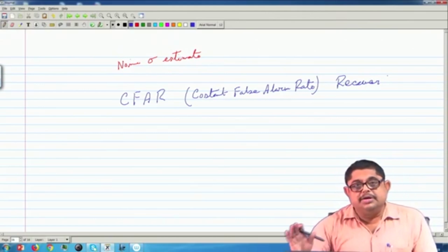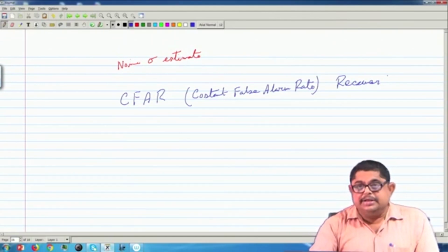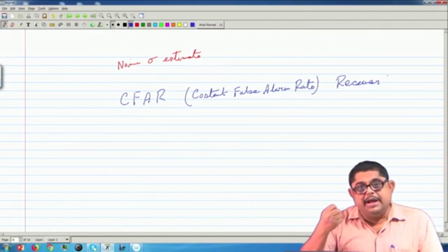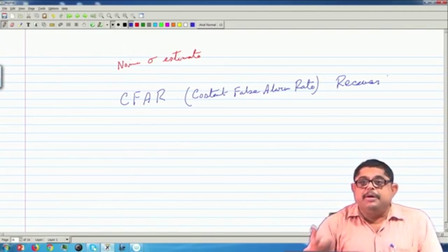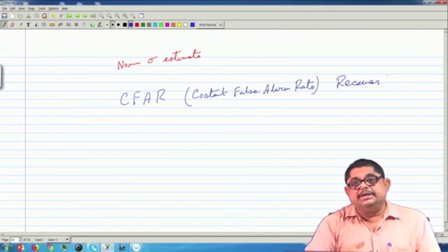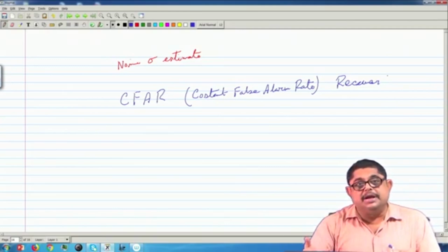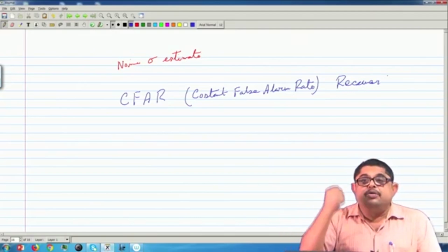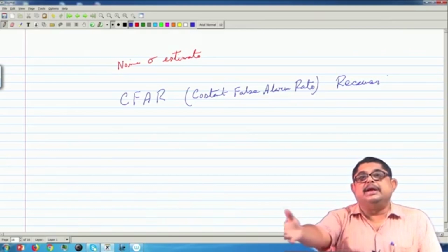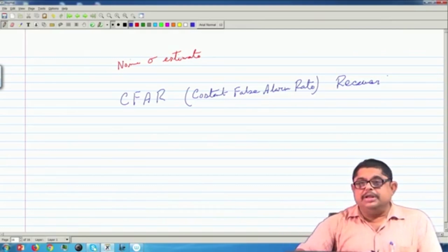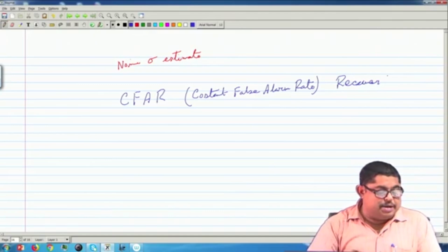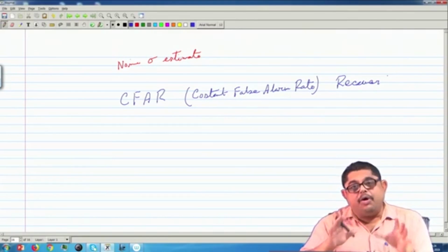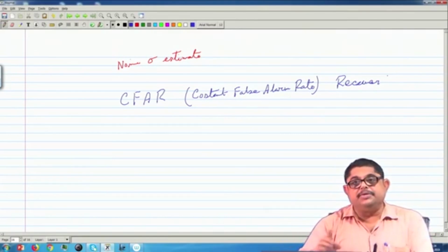With that I conclude this statistical detection. Now you know that if I am making any measurement, we have a probability of success, in this case probability of detection, and with a given probability of false alarm, that means with given noise statistics, we can always say that this will be the radar range. With all these things, that model is the modified radar range model. We have described that. With that, you can analyze almost all the cases that you will encounter in your professional life. Thank you.